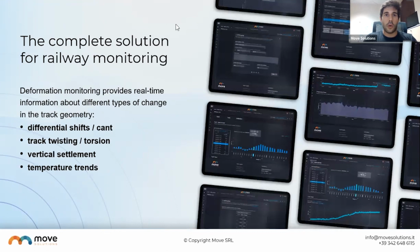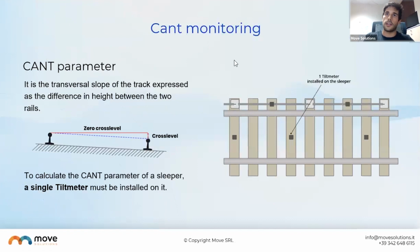So, when it comes to railway monitoring, what are we doing? First off, what's the purpose of railway monitoring? The idea is to detect certain parameters that help you understand how the tracks are moving and how they are changing in terms of geometry. There are basically 3 main parameters that we can detect. The first one is the cant, the second one is the twist, and then there is what we call the vertical settlement. Of course, we also show the temperatures alongside that information, because every single sensor has an integrated temperature sensor that provides the temperature along with the sampling.